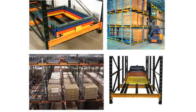There are some advantages though of pushback racks. One advantage is it can handle pallets that may be damaged. Damaged pallets can really create a lot of problems on drive-in racks, but these can handle pallets that may have a little damaged condition. They're much stronger for seismic conditions. If you have a warehouse located in a high seismic region or earthquake region, they offer much greater structural stability than a drive-in rack.